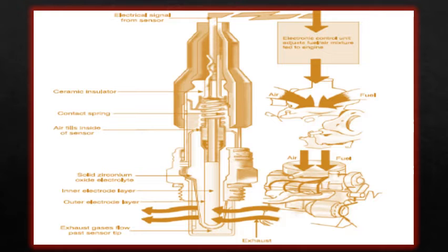A number of more recent systems have begun to incorporate a microprocessor to improve the accuracy with which the ignition is timed to fire the spark plug. Data is supplied to the microprocessor concerning engine speed, the position of the piston, and the load of the engine.